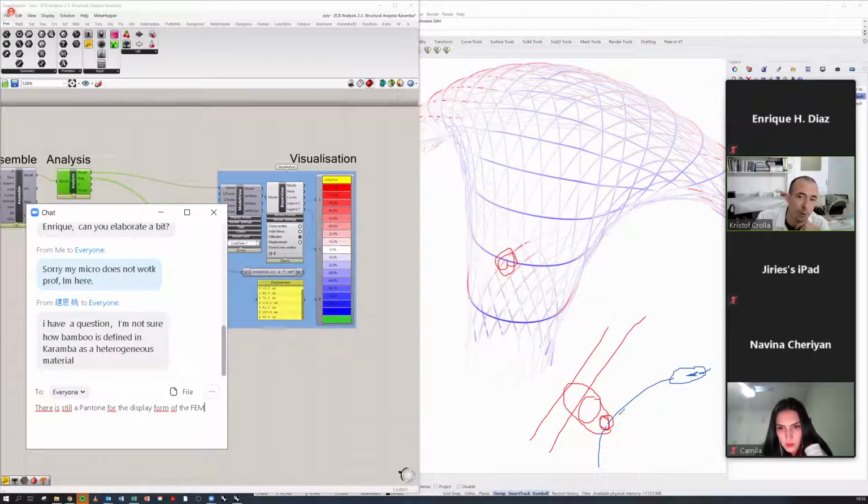But to identify how much you need to tighten everything is always a challenge. What I would do on site with a system like that is we would install the cables, and then we tension everything. You have these tools that allow you to measure how much tension you put on a cable, and we put everything under a light pre-tension, for example.